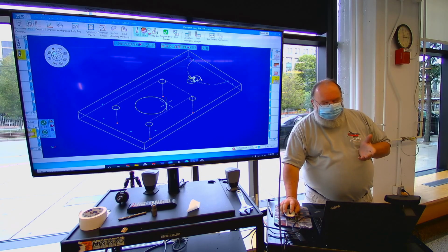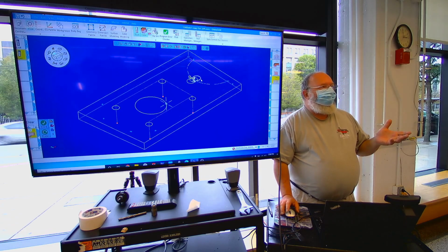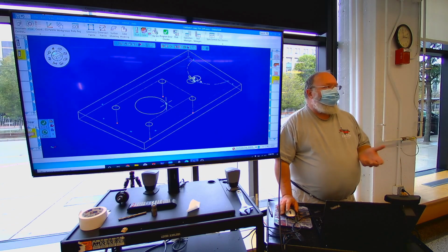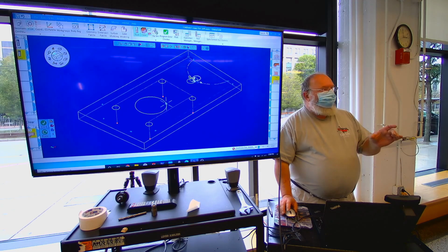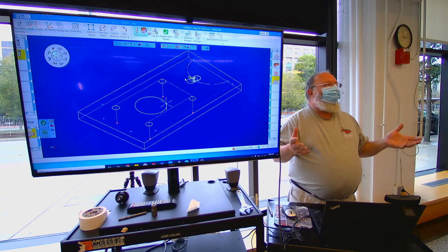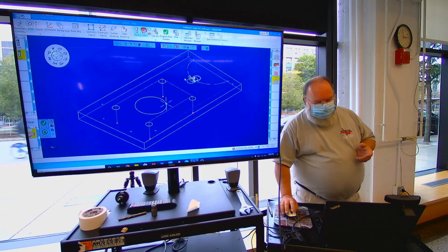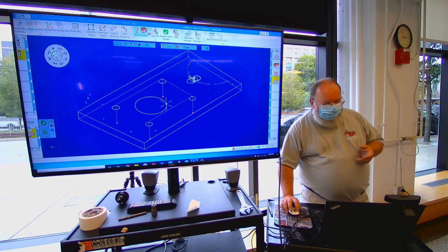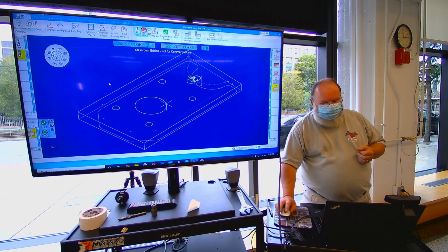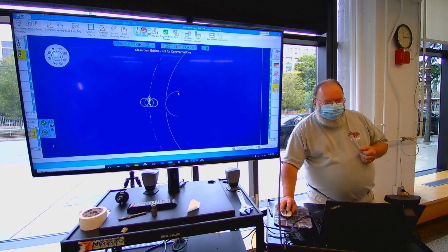The tool positions, basically tool left, tool right, tool on: inside, outside, and on. Outside, we're creating a male part. Inside, we're creating a cavity. On is, say, if we want to engrave something, we want to be right on the geometry. We don't want to be offset. So I want the tool on the outside in the climb milling direction. I say do that. If I look at this upright, you see my tangent entry and exit arc.